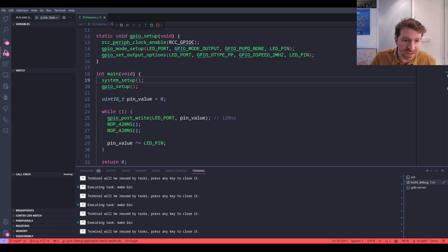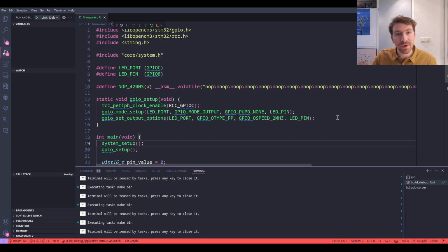This whole thing doesn't linearly scale, and that makes sense, right? It would be pretty convenient, let's say, for our random clock frequency to perfectly line up with increments of 10 nanoseconds or 20 nanoseconds or something. That's not actually how it's going to work, and the scope is not going to have a perfect resolution to get down to the nanosecond scale on these kinds of signals, because the signals do have transitions in them. It would be good to look at how those transitions look, so how it looks when we're transitioning this quickly, but I'm going to avoid that for now.